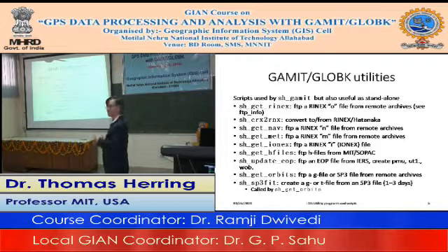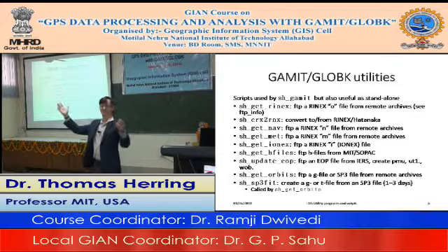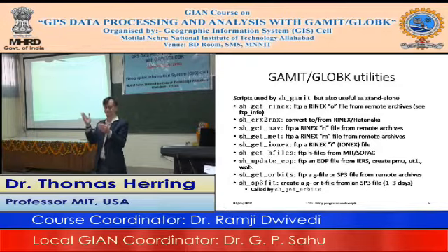Someone had asked in the class about these data files that ended with D rather than O. That D designation, you'll notice they're actually very small, is called Hatanaka compression. It's a specific compression for RINEX data. Since the range to the satellites mostly remains around 20,000 to 24,000 kilometers, each epoch doesn't change that much, so Hatanaka only outputs the bit that changed. It's very similar to the way image compression works.